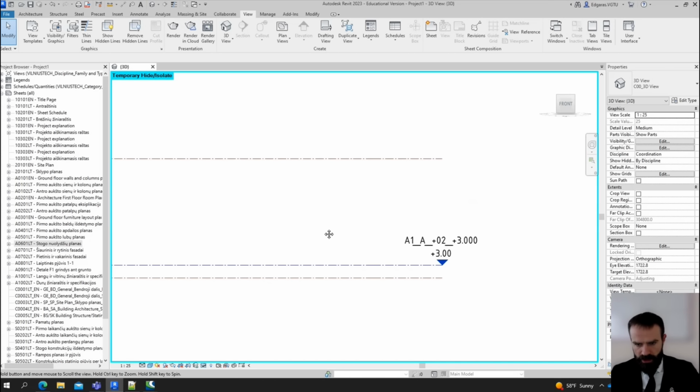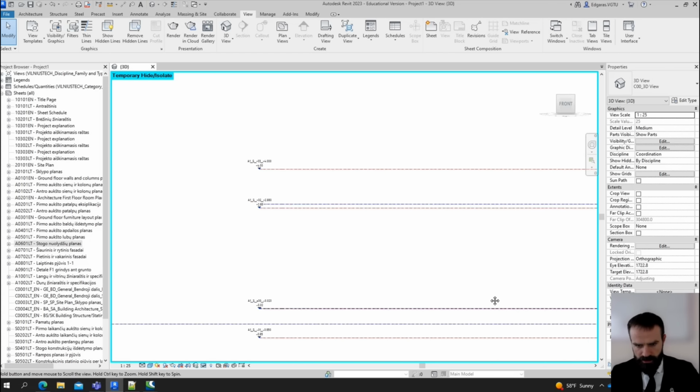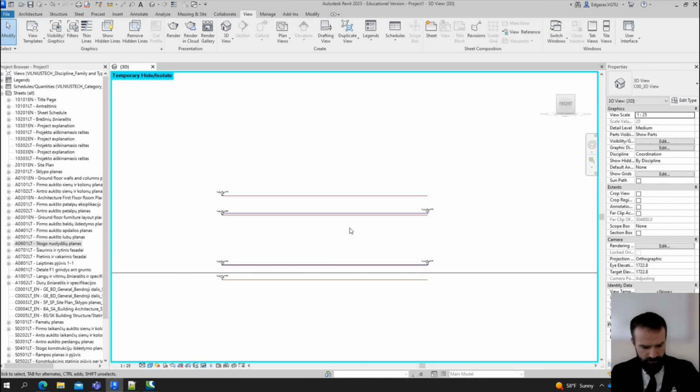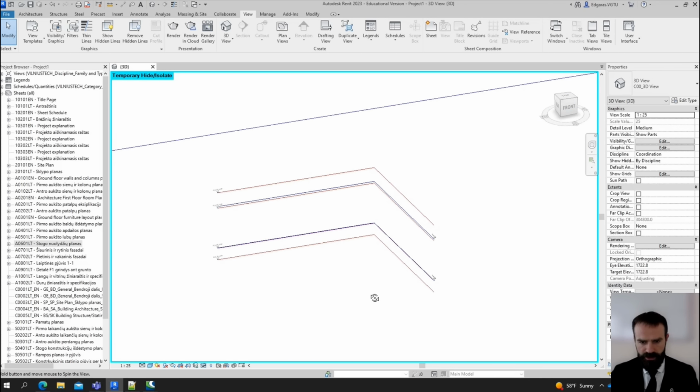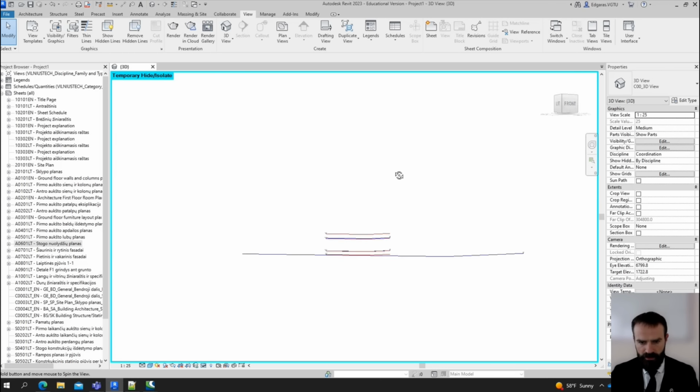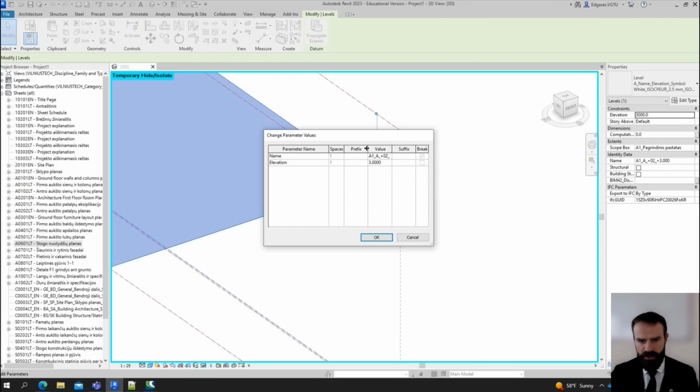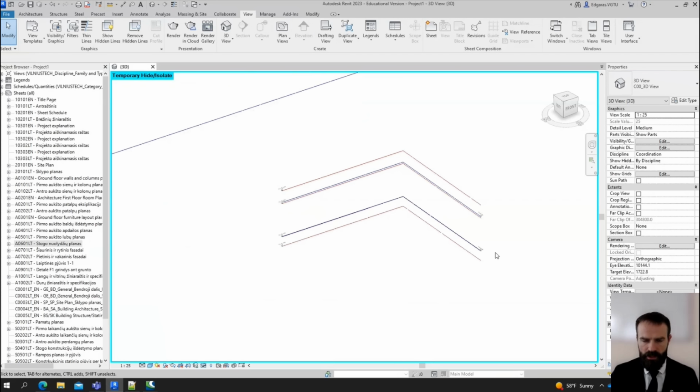Okay, so regarding levels, I explained. Depending on how many floors you create, create levels and make corrections on level size. If you double tap on it, you can just type and change the elevation and change the name. So always the elevation should be the same number here and the same number here. So it represents elevation.